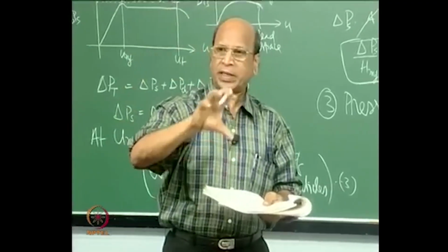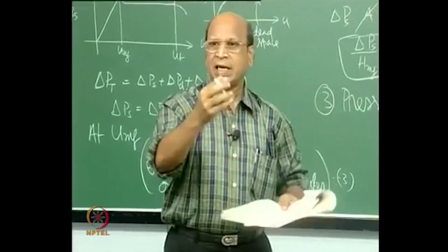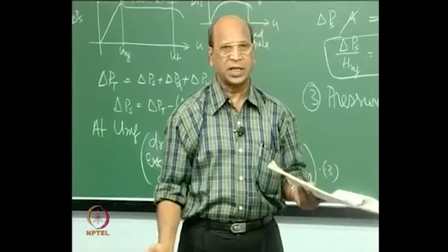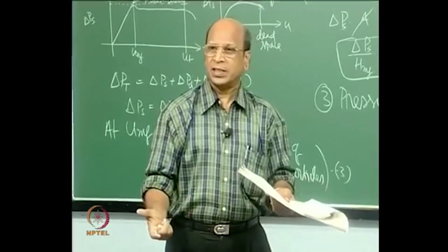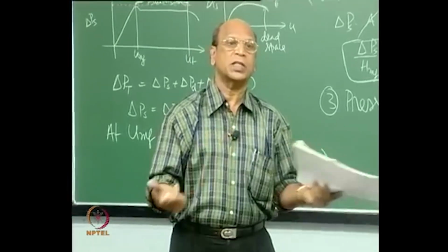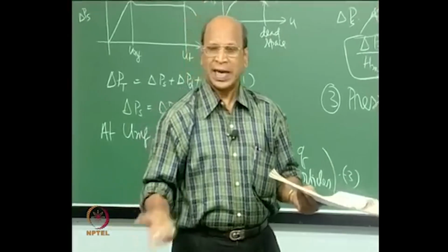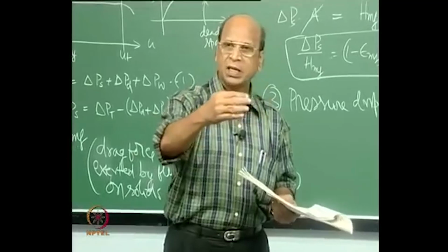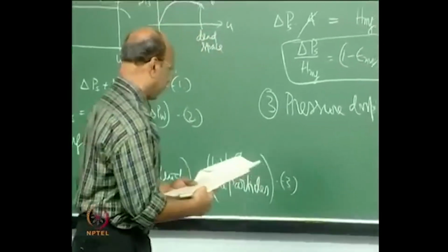So, for every 1 meter you put one piece, and that is connected, and you can see a very beautiful structure in those packings. Industrially these structured packings are also available. What is the use of structured packing is that I know very clearly what is the surface area I am going to get. That is all, more clarity. A random packing I do not know unless you measure it, and every time you change packing, every time it changes, right. So, that is the reason why random packings we use.